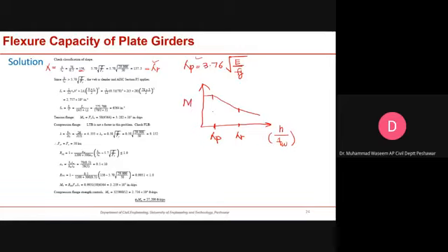Okay, so you have calculated your h by t, and this value is 156. The lambda r limit starts from 137.3. Since this value is greater than lambda r, it falls in this range. In this range we have a definite limit, and anything which falls beyond this limit we classify as slender.